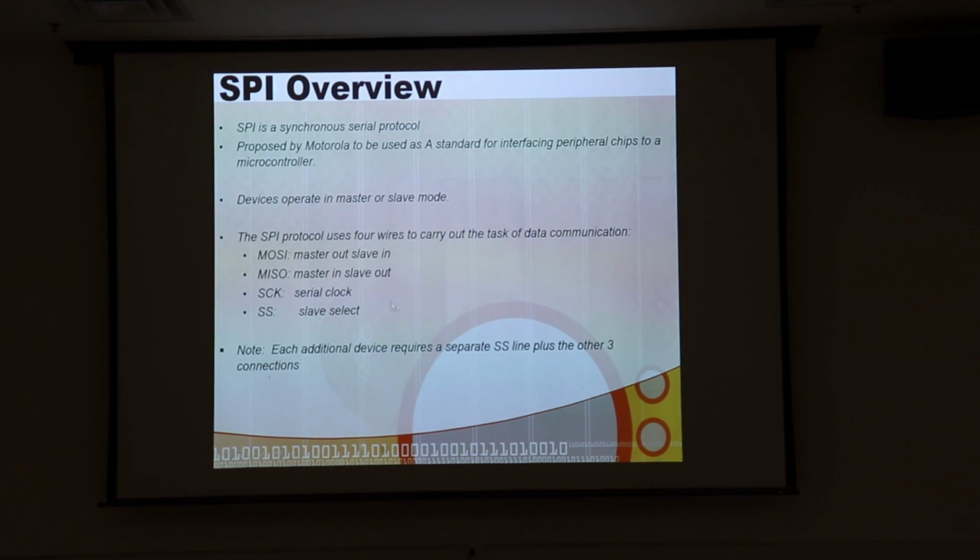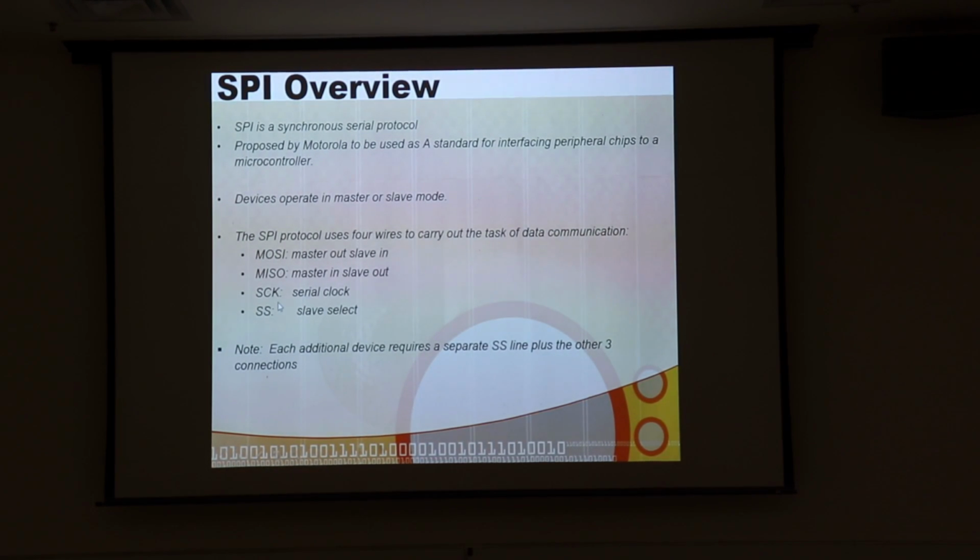So that's why you need a slave select. So if you have a master and 2 slaves, then guess what? On the serial data out line from the slaves, you have to tri-state those lines with the slave select line. So if your slave is not selected, it must tri-state its lines. Otherwise, one slave would be sending out highs and lows, and another slave would be sending out lows and highs, and they'd have short circuits on the bus. So that's not going to work. So they definitely have to tri-state their serial data out line if they're not the addressed slave.